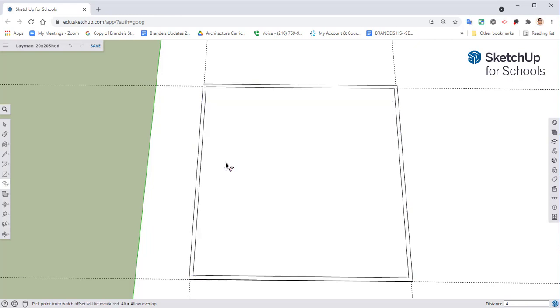The reason we're going to use 4 is because the overall wall is going to be the width of a 2x4 stud, which is 3.5 inches. That stud is going to go all the way to the outside of our foundation, and then on the inside we have a 1/2 inch sheet of drywall. So our outside wall will be 4 inches, and then our inside wall we will make it 4.5 inches, so that way it will mimic the 1/2 inch drywall on each side.